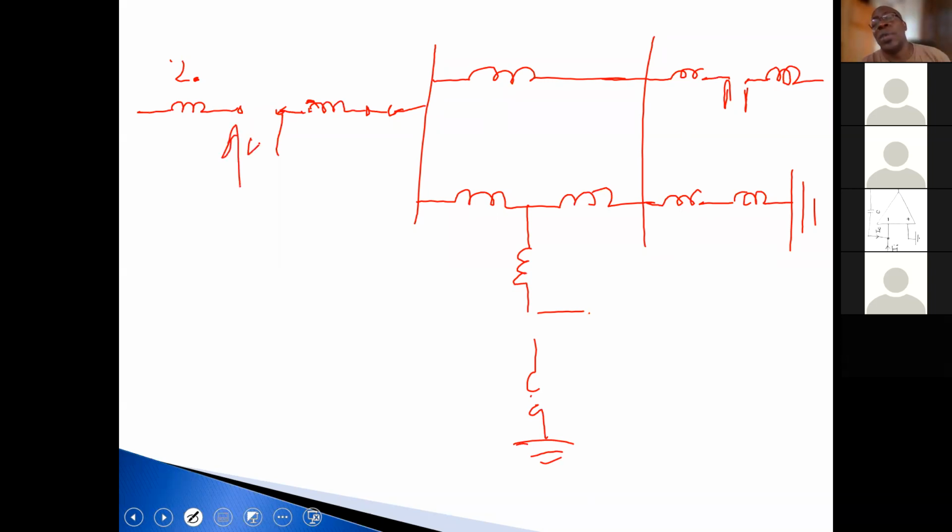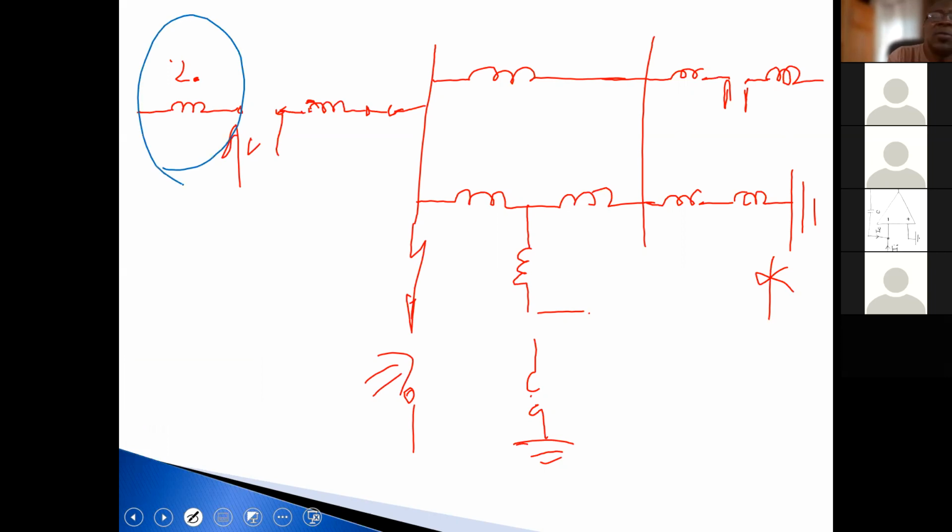And what this is showing you is that there is no zero sequence based on the fault on this bus. No zero sequence will be going to any other generators, apart from this one over here, because you have the delta winding or an ungrounded star. Okay? And so for this fault point, when you're looking in, it means that this would be removed from the circuit, this would be removed from the circuit, and that would be removed from the circuit.